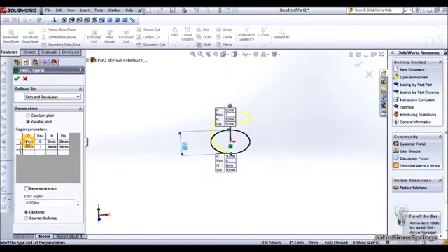To start off, I'm going to start with a pitch of 2 millimeters. Now I'm going to go to 8.5 millimeters at 1 revolution. Then 12 mil, and that'd be at the second revolution, and then tab your way through to get to a new pitch starting or revolution.